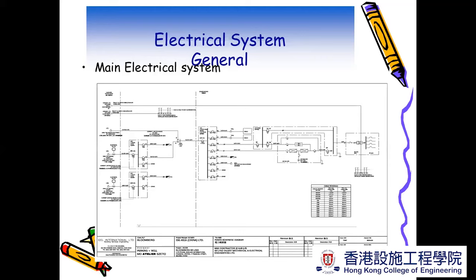Well, this drawing is too small, but I'll show you some other later on. But basically, you can see that the power supply comes through here and then goes to there through an ATS, I believe. Right, through ATS, and the ATS will select the normal power supply to supply to the distribution board, and from there go on to the UPS system. And this UPS will supply to all the IT load downstream, while this panel will also provide some other services of CRAC units or whatever inside the server floor.